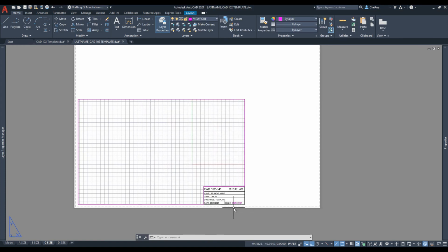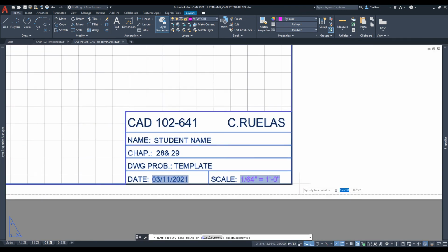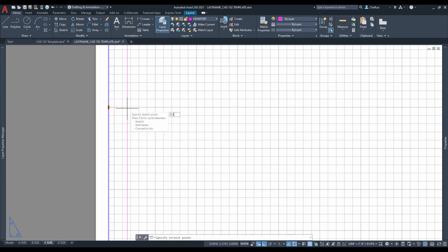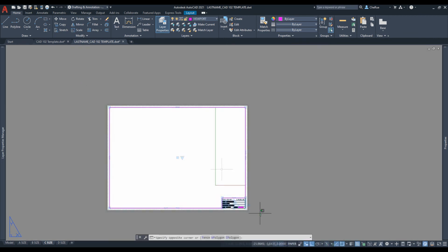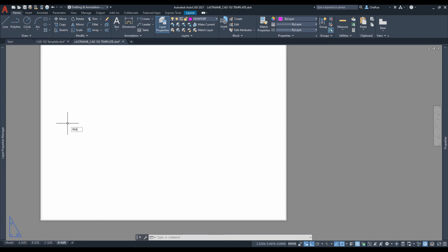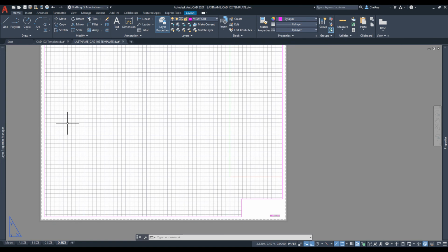It regenerates. All right, I'm going to move this again, and I'm going to repeat the same thing that I've been doing with the previous ones. I'm going to keep repeating this. Copy base, 0, 0, and D size, delete this, and paste clip, enter, 0, 0, enter, regen, perfect.